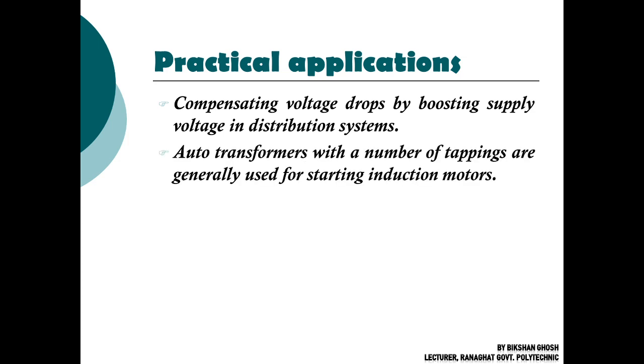Okay, next, autotransformers with a number of tappings are generally used for starting induction motors, basically three-phase induction motors. We know that at the time of starting, if full voltage is applied, a huge amount of current is basically drawn by induction motors. So with the help of autotransformers, a reduced voltage can be applied to the induction motors so that a lesser amount of current is being drawn from the system. Thus, autotransformers are very efficient devices for starting three-phase induction motors.